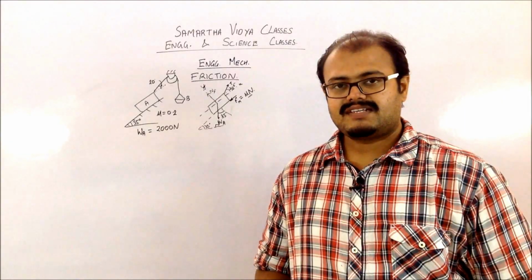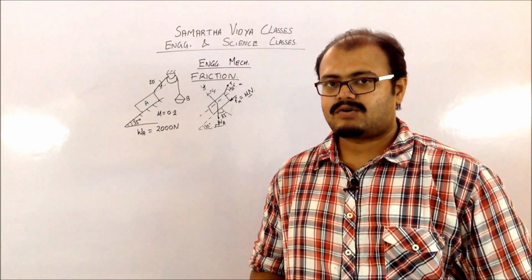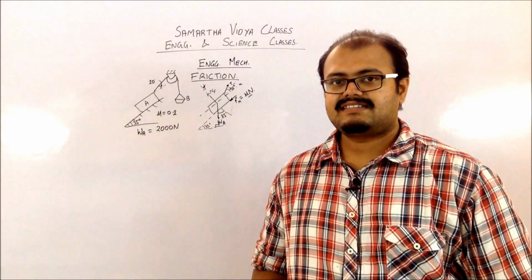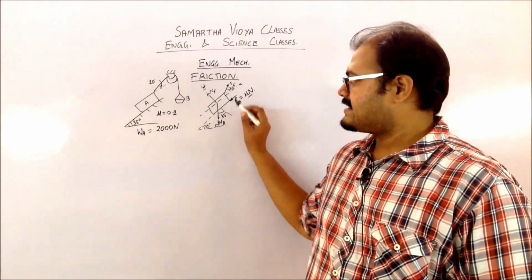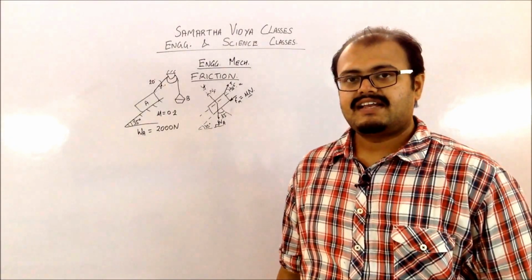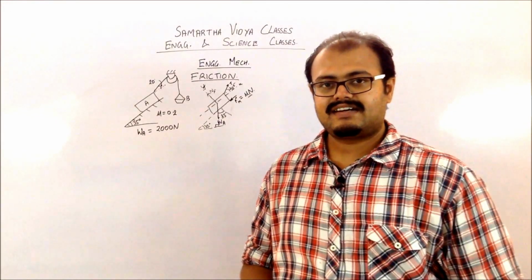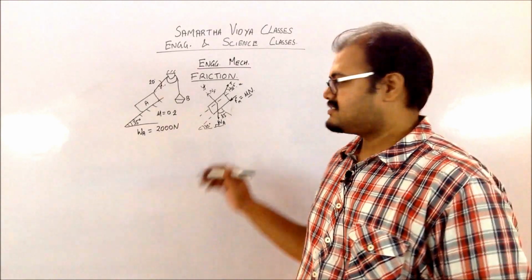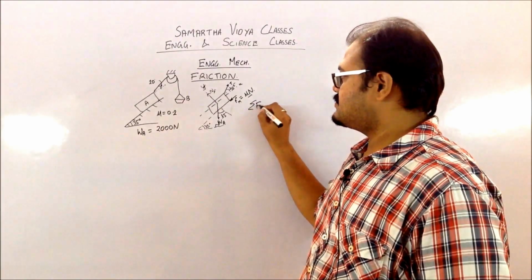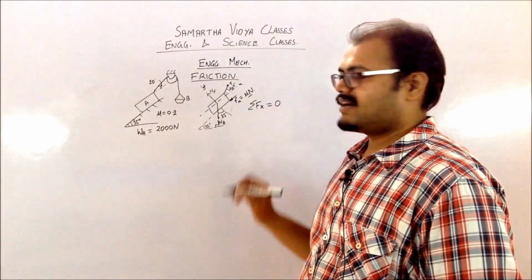So basically what you can see is that engineering mechanics is all about the geometry of angles and triangles. So you have already determined all the angles for the different forces. Now you need to write their corresponding equations. Since we are solving for equilibrium, your conditions are going to be summation Fx equals 0 and summation Fy is equal to 0.